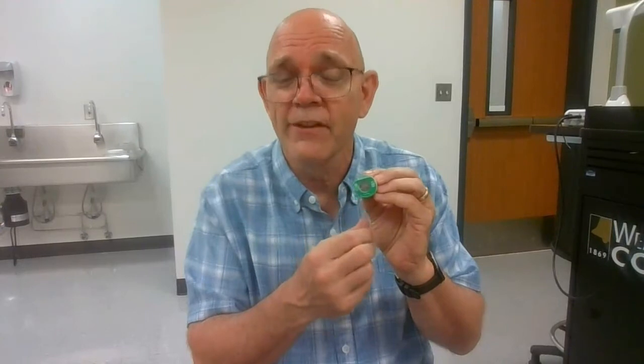So people said, since that's about the size of a penny and it's copper, I could just stick a copper penny in there and it will still work, which it would. But unfortunately, something was making it get too hot, and now you have a penny in there. That penny's not going to melt like the little wire in there would and protect your house. And so now you might burn the house down, especially if you forgot to get the fuse on Monday or Tuesday or Wednesday and let it go for a while. It might very well burn your house down, rather than fixing whatever the problem is that's causing too much current going through there.